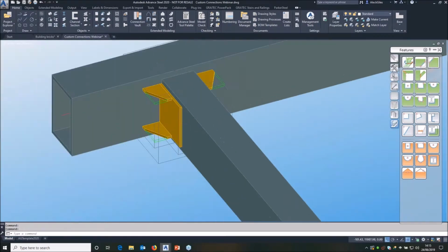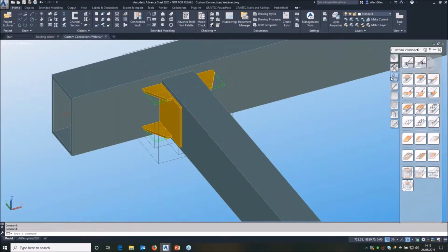Need to bolt these 3 items together now. So I'll go back to my building rigs. I don't just want the bolts to be anywhere. I want the bolts to stay the right length, but also if this plate changes length, I want it to stay in the middle of the overlapping area of the 2 items. So I could just do a set based on the middle, but you'll see later on we can adjust the offsets and things. So I still want to have the bolts intelligently located.